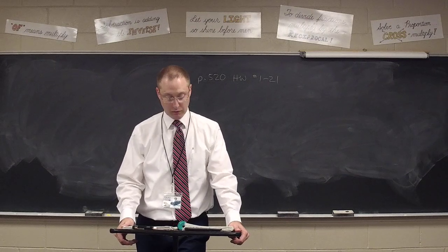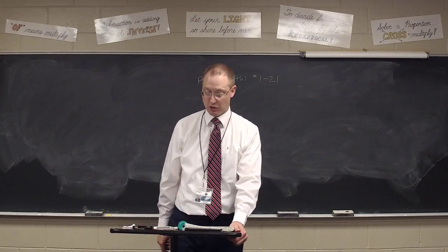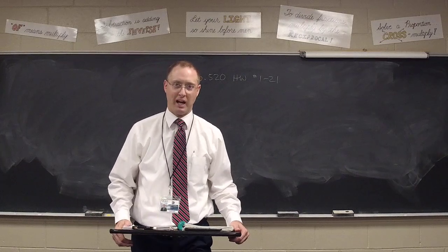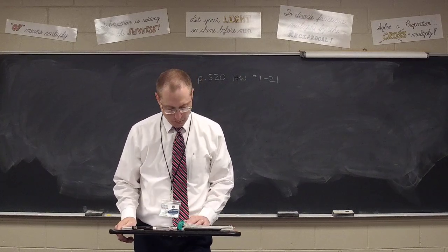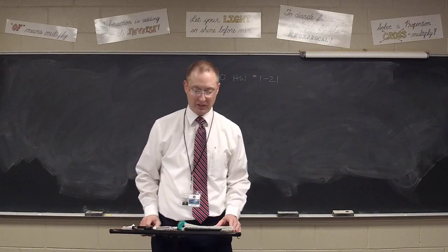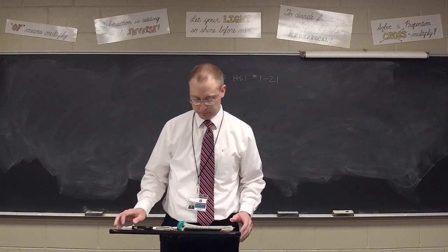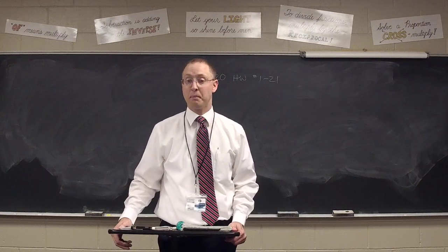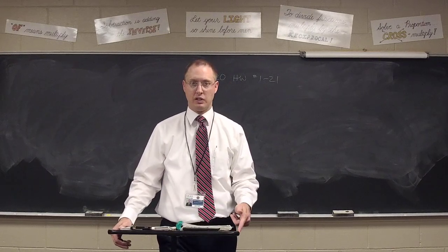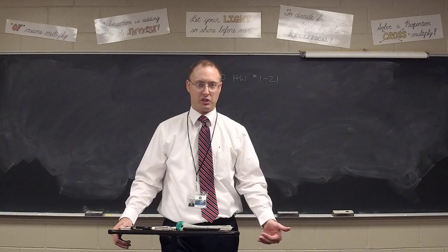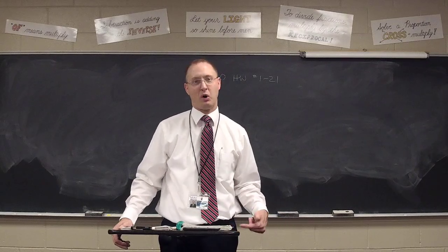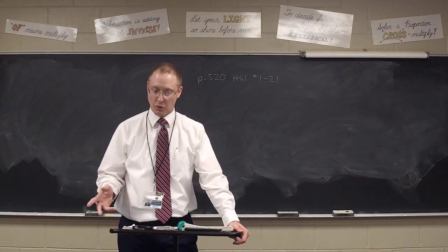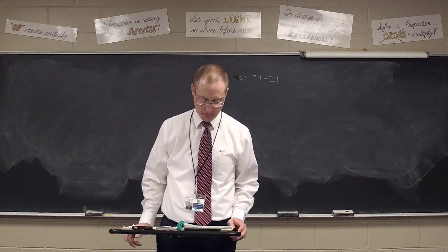And letter C, how do the resistors' voltages compare with the voltage of the battery? The sum of the voltages used equals the voltage provided by the battery. Number 20, how is equivalent resistance determined for resistances in parallel? The equivalent resistance is calculated by finding the reciprocals of the individual resistances, taking the sum of those reciprocals, and then taking the reciprocal of that sum. So it's a lot of reciprocals, kind of like with the thin lens equation or the mirror equation.